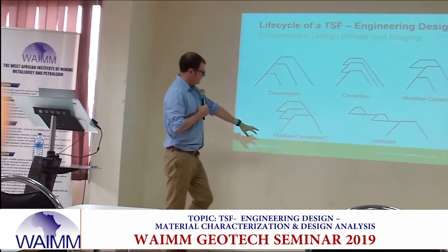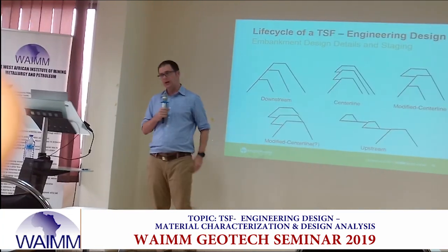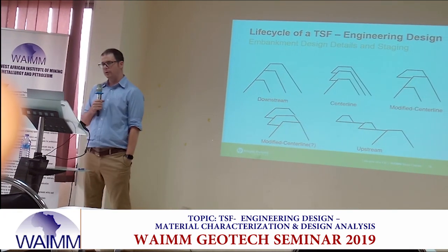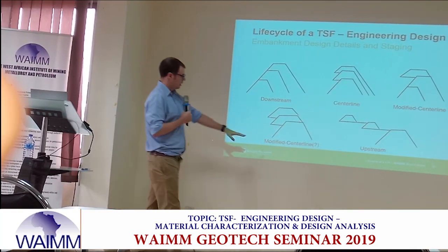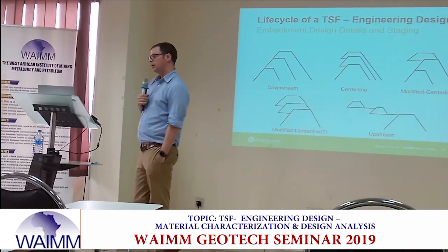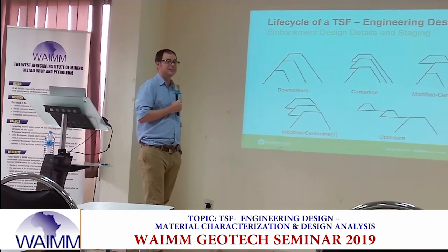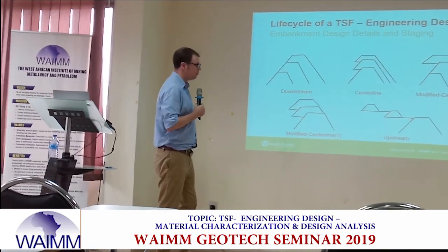Then we have something like this. Some people might call this modified centerline. Some people might call it upstream, where we just kind of march upstream with each raise. The benefit here is our costs go way down. The risk is that we're now much more reliant on the strength of our tailings, which is problematic.